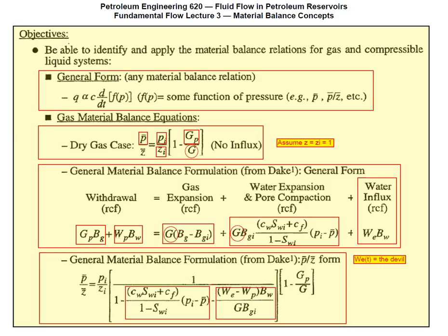What's the first thing you learn in simulation class? You must have material balance. You track it, and it better be something like 10 to the minus 10th percent or 10 to the minus 12%. So a fraction of a billionth of a percent, that sort of thing. Am I in the right ballpark here, people who specialize in simulators? This is something that's printed out. They check it all the time because you're absolutely right. Your simulator cannot leak. It cannot create or destroy mass. So that has to be accounted. Excellent questions. All very good.